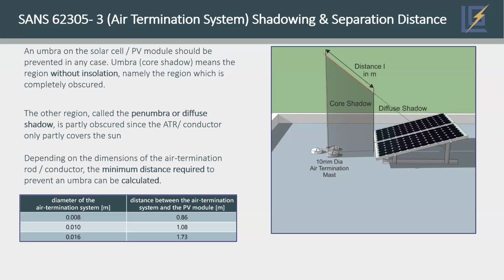Depending on the roofs, it also becomes tricky because the brackets you get from Lumax, from K2 or any alternative company, often have anodizing, so there's no bonding. The problem we face is that SANS 10142 says that anything you put on top of a roof that is a steel structure shall be bonded.